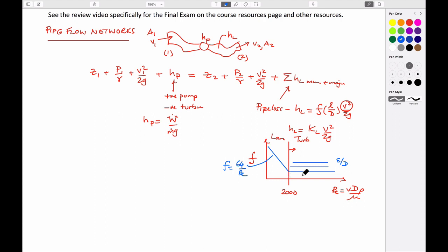And so if you double the flow velocity, the magnitude of the friction factor doesn't change. And so in using that in this expression here, the dependency of the friction factor on velocity ends up being a square term. One of the velocities gets cancelled out if you use Reynolds number. And so the forms of solving the equations to do that change.